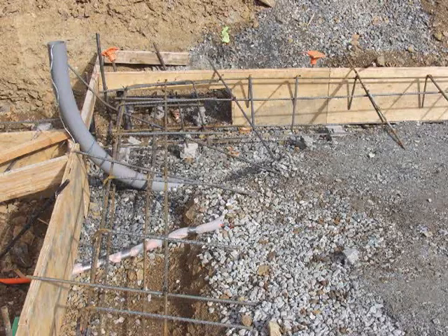Now you need to check with your local power company. Most companies don't want more than about 270 degrees of turns from where the power comes from its source into the building. So here we've got our 90-degree sweep coming up right to our panel location, and we've got a pull string in there, and like I say, we've been sure to set it up so that we don't have more than 270 degrees worth of turns.